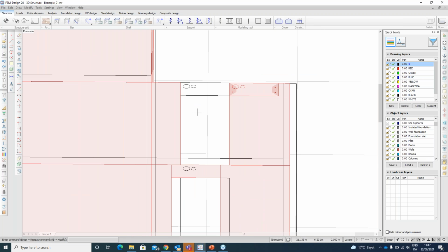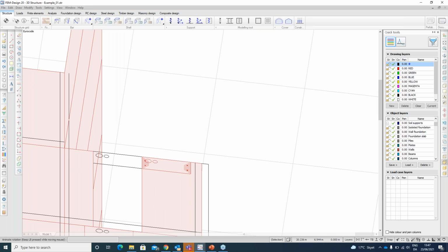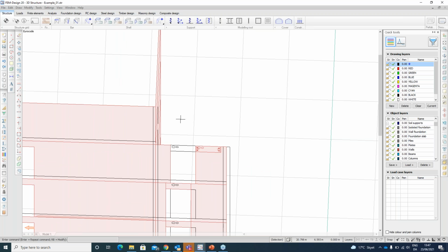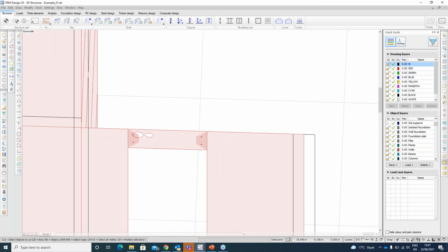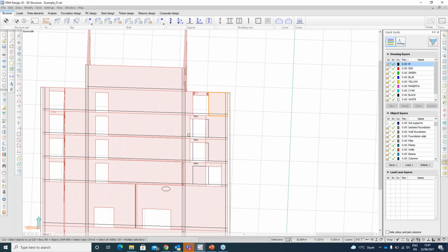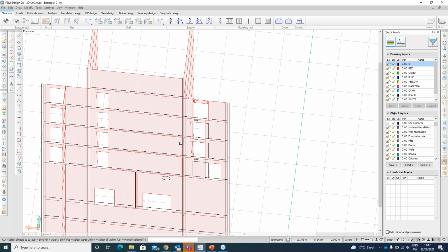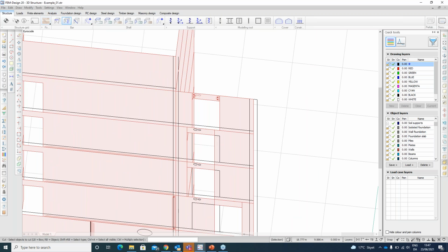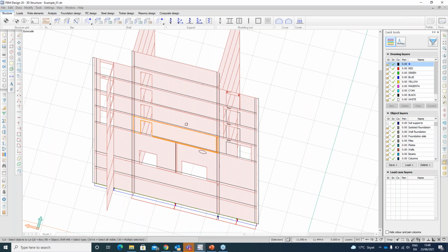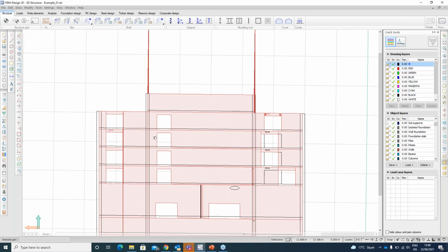So that's why I'm saying this is not the way you do it. I'm not saying that. This is a way to do it. The most important thing is that you have consistency in your mesh. That's the most important thing. Can I revert this? So always after making a modification, you generate a mesh and check.